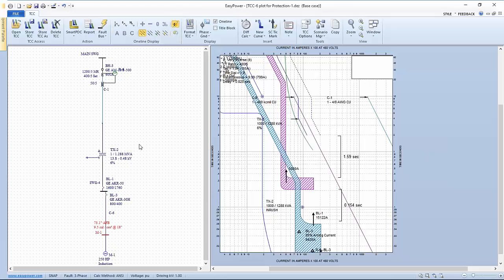So if we look at the incident energy over here for this bus, which is the one I'm faulting, you can see that just by backing off that set point a little bit, we have a better incident energy, because the breaker can use, or the tool can use, the 100% arcing current to ensure clearance.